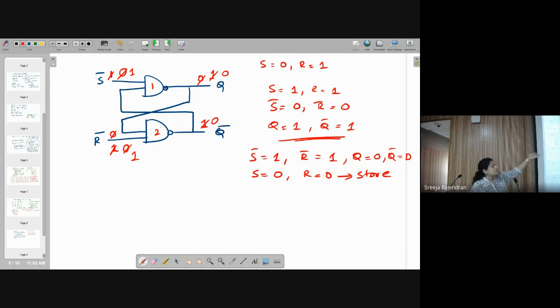A single two gate circuit is fine, but when you have large circuits, the delay will accumulate, or there will be a difference in the time taken or the propagation delay of each gate, though it is of the same functionality, will not be the same. Okay, that is also there.